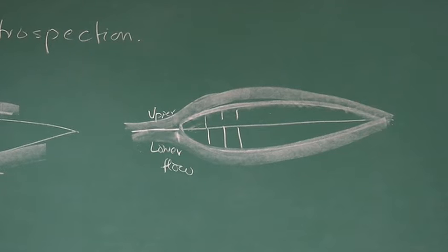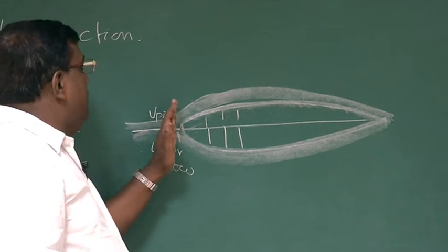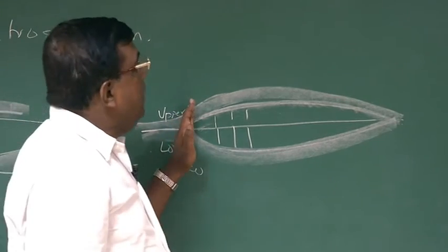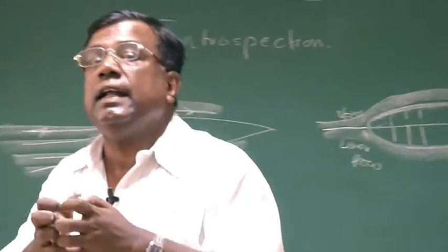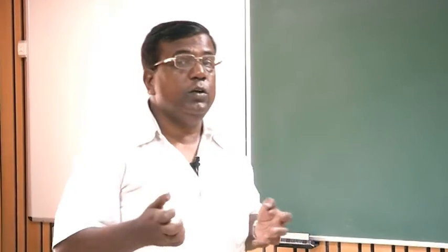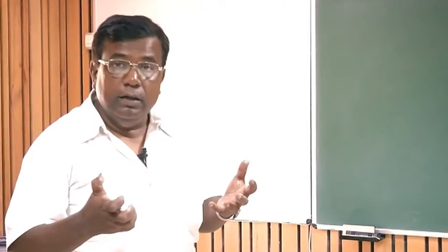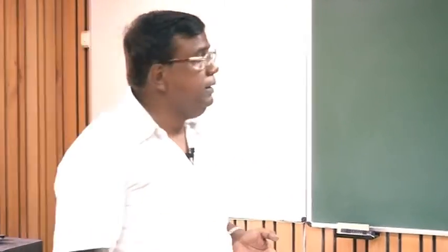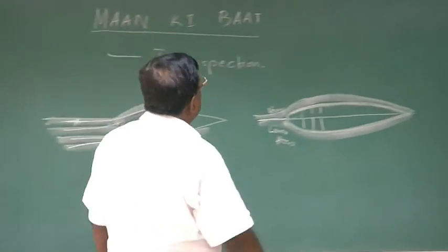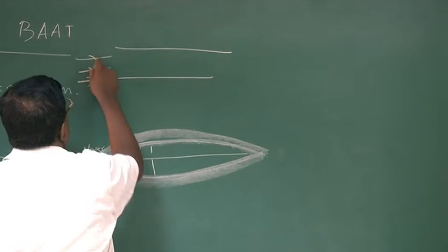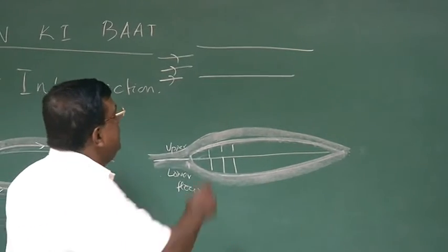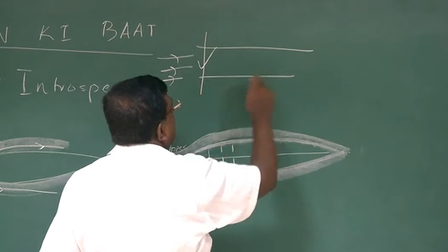Okay? And there is another law of justice or natural law: whatever fluid is coming here has to come out. It cannot get stagnated at one point, right? It cannot get accumulated at one point, which we call the continuity of the fluid particle motion. That is, if we try to draw a pipe and I allow fluid to flow through the pipe, I know that whatever is going in here has to come out.